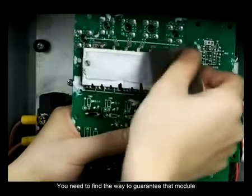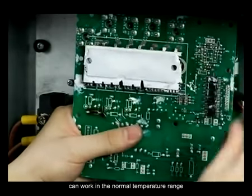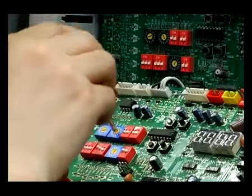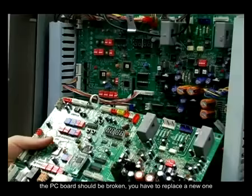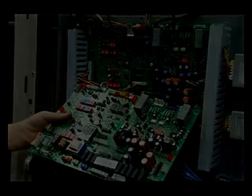You need to find a way to guarantee that the module can work in the normal temperature range and wipe the thermal silicone grease well. After the above repairs, if the malfunction cannot be solved, the PC board should be broken. You have to replace it with a new one.